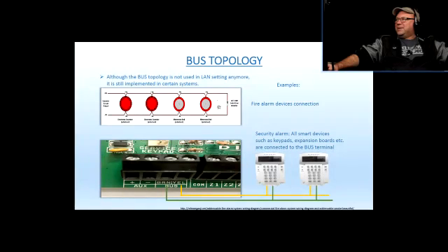But if one of the devices of the system triggers, like let's say there's a smoke detector here, I can even see that myself. Let's say this is a smoke detector. The circuitry of that smoke detector detects smoke and it triggers, which means it shorts out. So then the system is going to see a short there. Now it's going to react as if there were a fire.